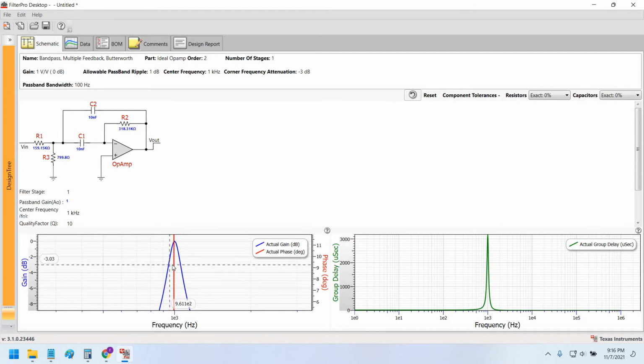Okay, now let's see on the other end, that is minus 3 dB. Cutoff frequency is 1.0576 into 10 to the power 3, that is 1057 hertz, that is 1000 plus 50 hertz, that is also very accurate. So we got the very accurate frequency response curve here,